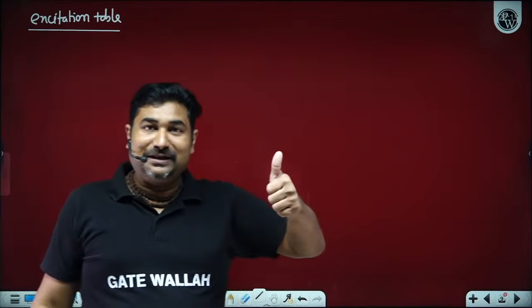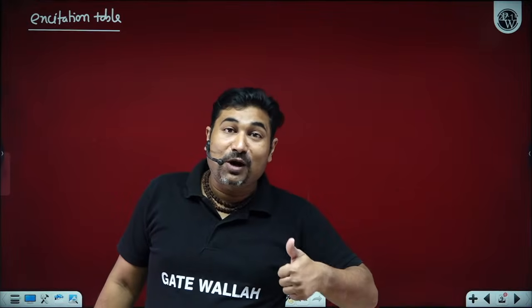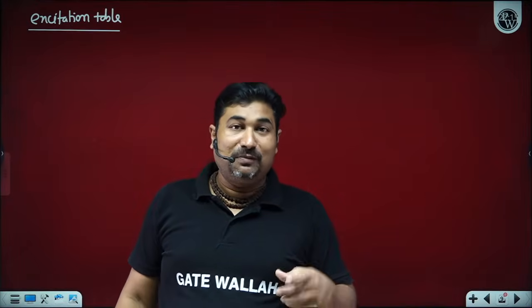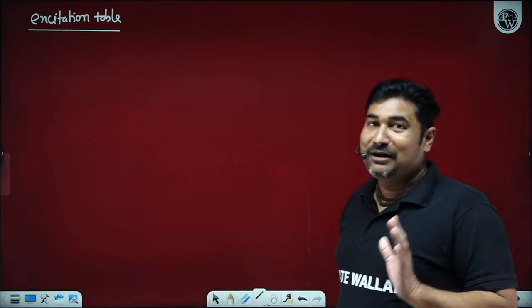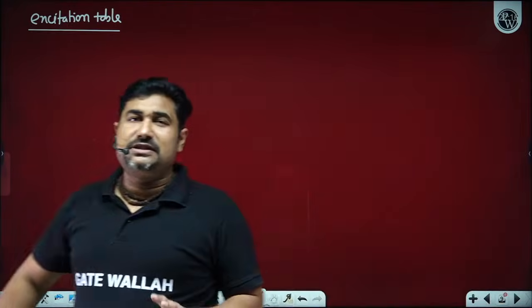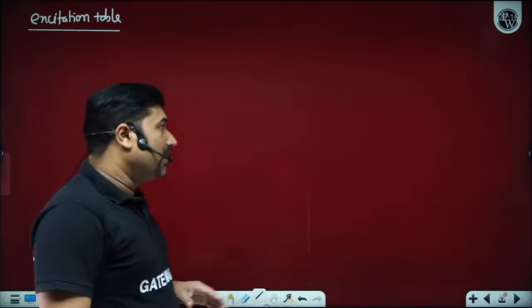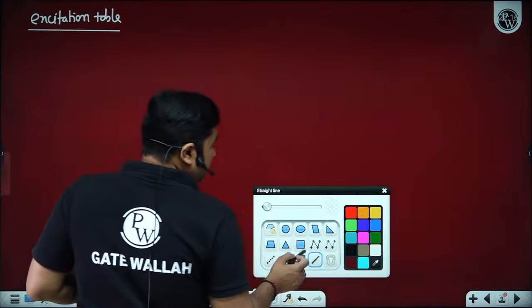And one line is, before applying clock pulse, first find input to the flip-flop, apply the clock pulse and follow the truth table. That is all you have to do. Any question based on the sequential circuit can be solved. Now please observe excitation table.